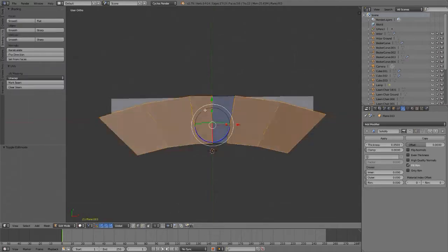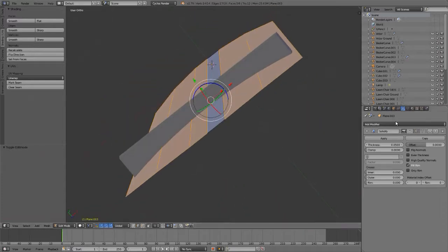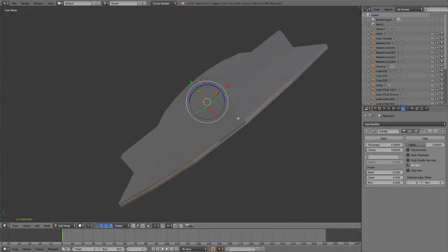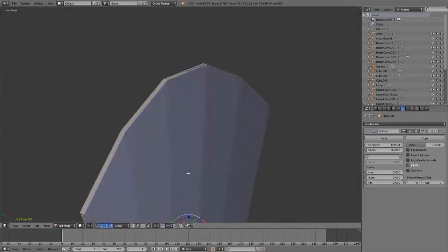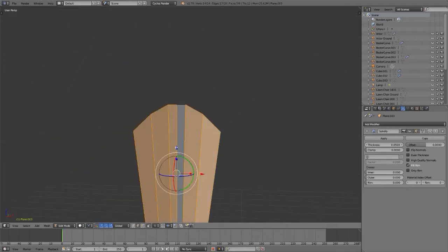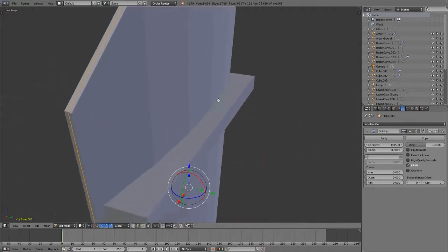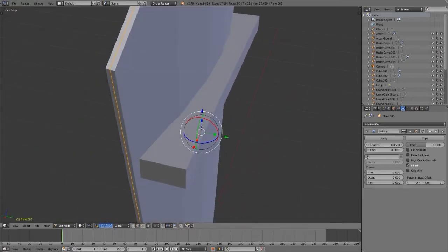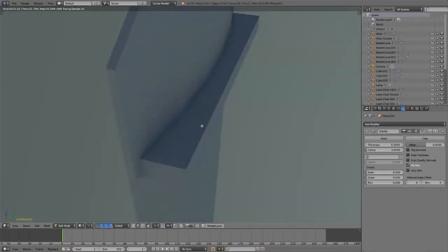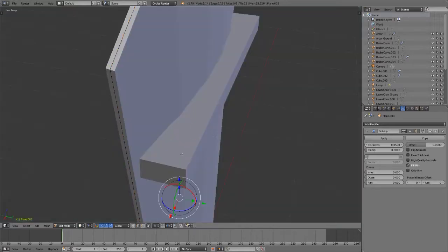So now it matches roughly. Gosh, that's so hard to look at. Edit mode, 5 to go into perspective view, and then T to hide or reveal that tool shelf. The easiest way to see how you're doing is to look at a rendered view. Is there any little tiny bit of shadow here? No, there's not. I want a little tiny bit of shadow.